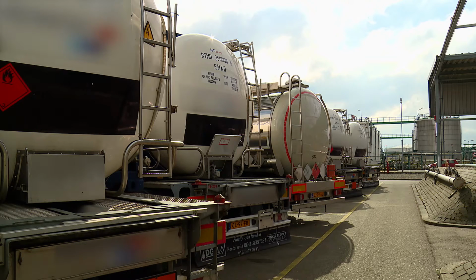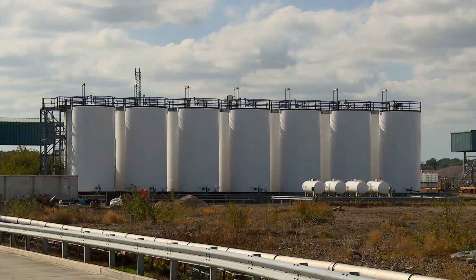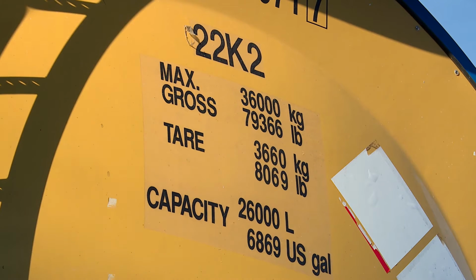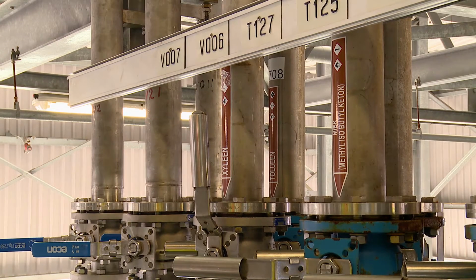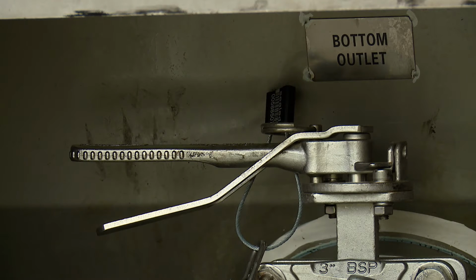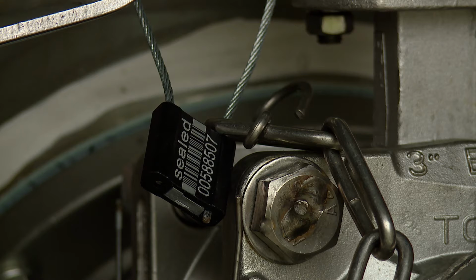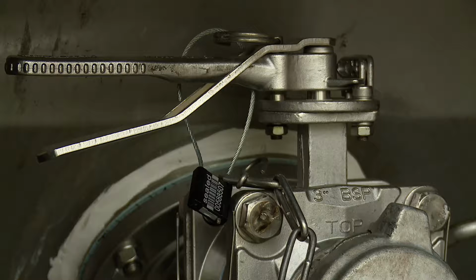In order to ensure that the correct product is loaded into the correct vehicle or storage tank in the correct quantity, both the driver and site operator confirm that the vehicle connects to the correct product storage tank and that there is sufficient space to receive the volume. When offloading, if security seals are present, these will be scrutinized for evidence of tampering with the product whilst in transit. They can also be cross-referenced with consignment paperwork.